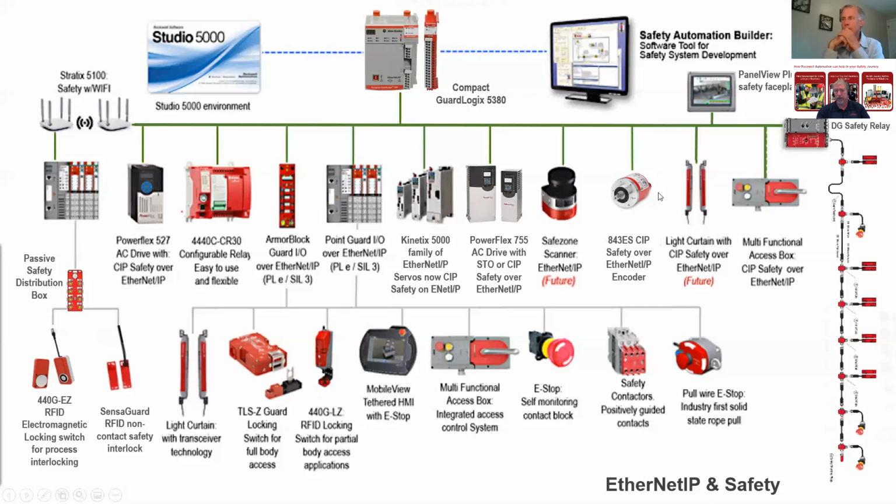light curtain. Now coming back over here, this product is actually not CIP connection, but it's an Ethernet connection for diagnostics. So we can utilize a separate safety control in various little applications that we can get the diagnostic information directly up into our main control system. So the safety is managed and maintained separately, but the connection to the Logix controller provides the information as to what's going on in that particular controller with safety, okay?